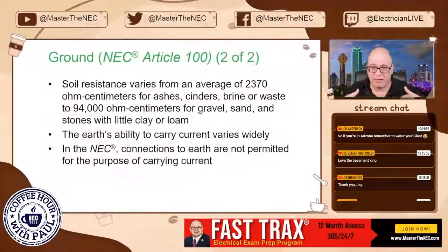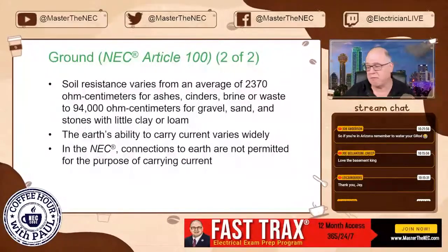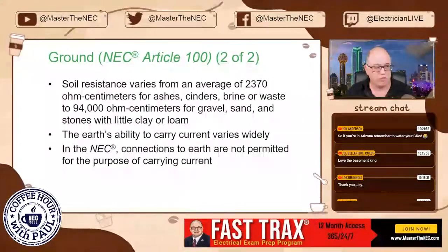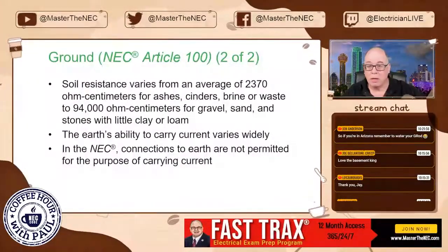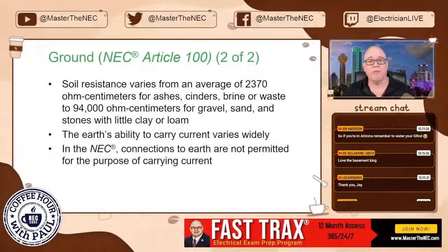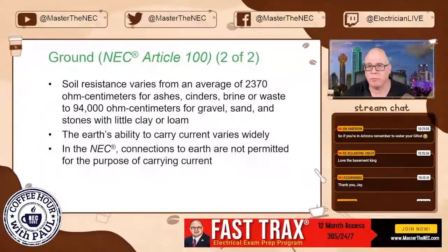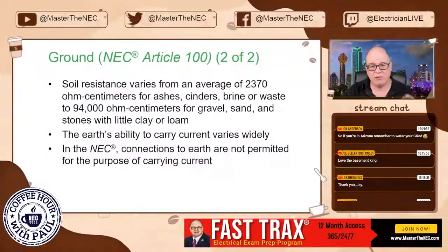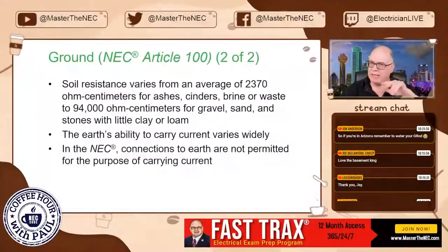Never, ever, if you're ever in an installation or you talk to an apprentice and they say, well, we'll just drive a ground rod over here because we didn't run an equipment ground, the first thing you should say is no, but it should be hell no, because you can never use the earth for what we do as electricians as a return path, ever. The resistance is too high and it's unknown. So we can't do that, all right? But we'll get into that, don't worry.